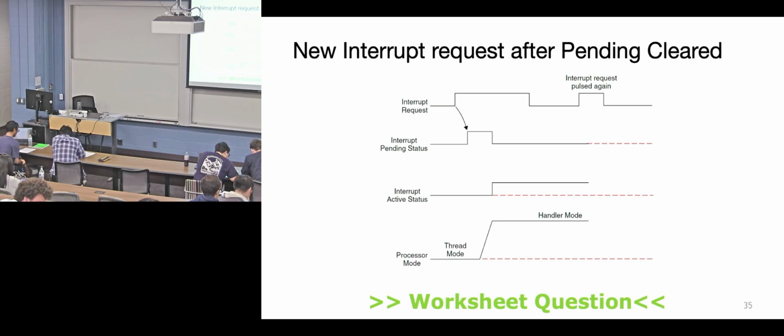Active goes low on its own time, and then it can release pending to go high. Okay, so pending can't go high while active is high. Correct. Very cool. So we're definitely still active here. Here we're going down. The pulse has already happened, but there's a time delay so that pending can go back up now. If you draw those lines just right, there's still time for that thing to go high. Okay.